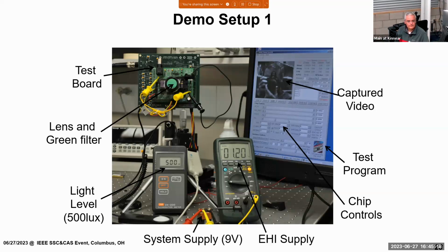I guess I'm curious, why did you use the heat filter for this? Well, typically, we use the green filter to kind of emulate, because this one has lots of stuff, infrared and stuff. So we don't really want that infrared or UV to create more charge, and we make sure that a single light is coming through and we know exactly what to expect from it. Most of the time, they don't tell you this, but they use the green filter with 10 nanometers for all image sensor specifications. Although they report the full bandwidth, most of the specs are at a 550 nanometer plus or minus 10 nanometer filter. So it's a habit from industry, so you have to use it.